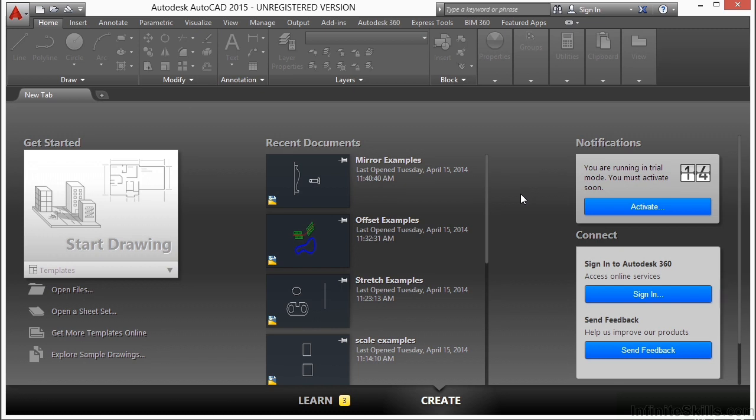Many times in your drawings, you're going to need lines to get a little bit bigger or a little bit shorter. You will also need your lines to abut up to other lines. That's where the trim and the extend commands come in. Now, I've combined these two commands together because they're practically identical in function. In fact, with a little bit of keyboard magic, you can even trim or extend with either the trim or extend button. So the trim command will shorten your objects by cutting away the parts you don't want along a cutting line. Now the extend command will lengthen your lines up to an extension line.